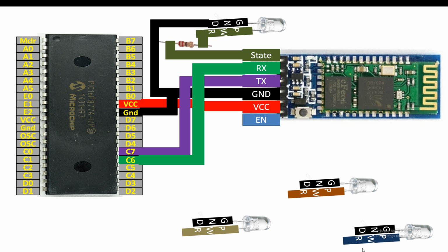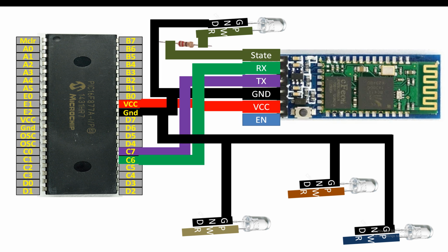So for that purpose, we need to connect these LEDs as well. So let's connect them. As you know, each LED has 2 pins, one longer, one shorter. Shorter is the ground, common them and send them to the common ground. And for the longer pin, you will need a 220 ohm resistor for each LED like this. Now for the rightmost LED, okay, let's start with the top LED. You connect the longer pin to the one end of the 220 ohm resistor like this.